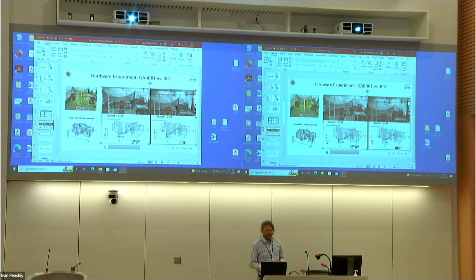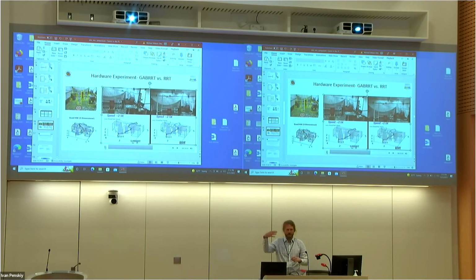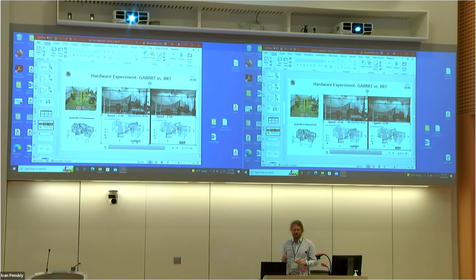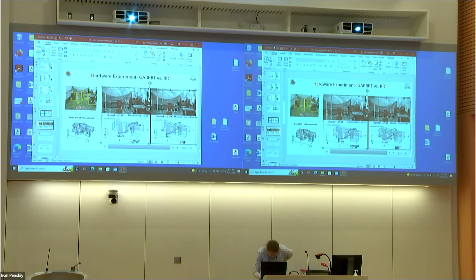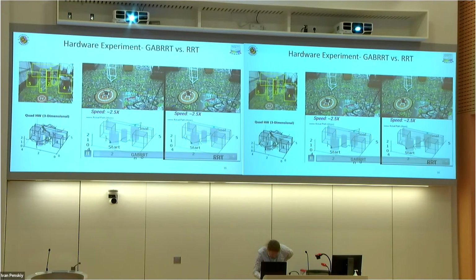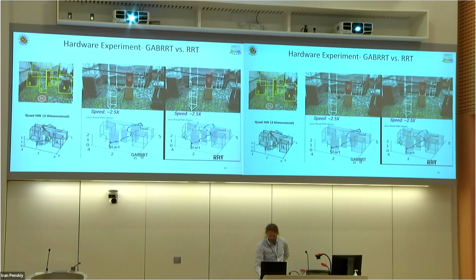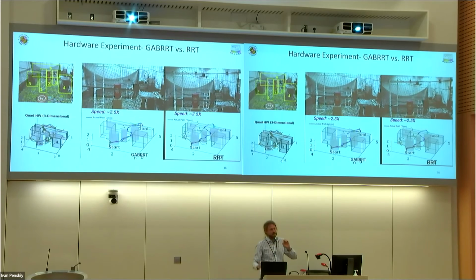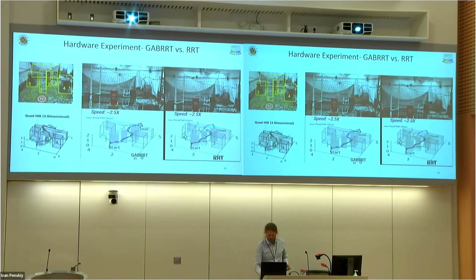These are experiments in our lab that Sharon ran, where we're getting around some obstacles. There's the pipe obstacle and the pad obstacle, and also a net that's hung in the background. So to get through the obstacles, we have to change height and also change XY location with the quadrotor. And we're comparing just to simple RRT in this case. So this is GAB RRT. This is where we are just using the holonomic reverse tree as a focusing heuristic for the quadrotor forward tree.